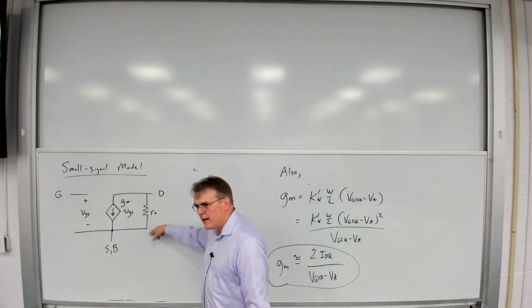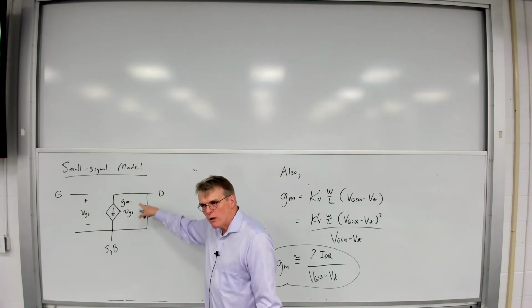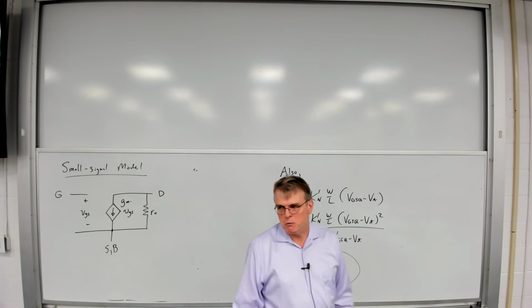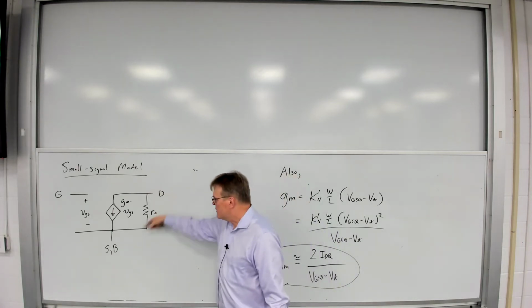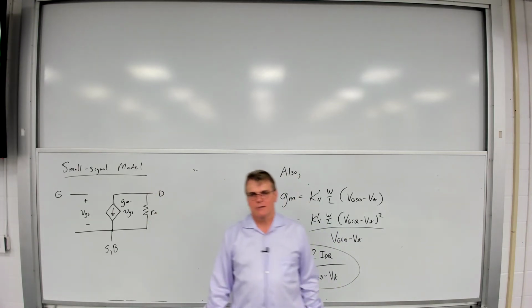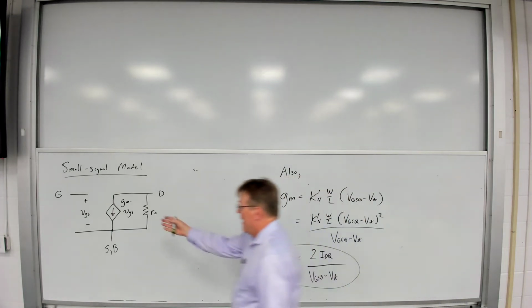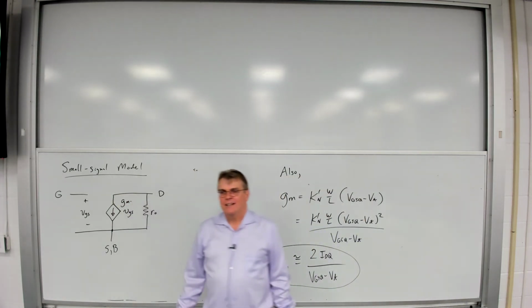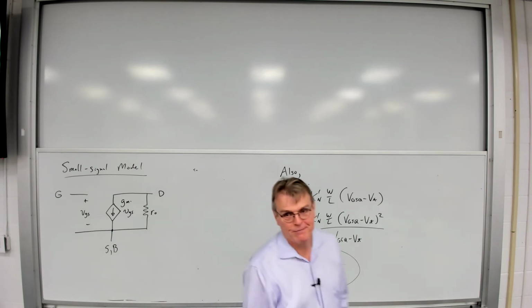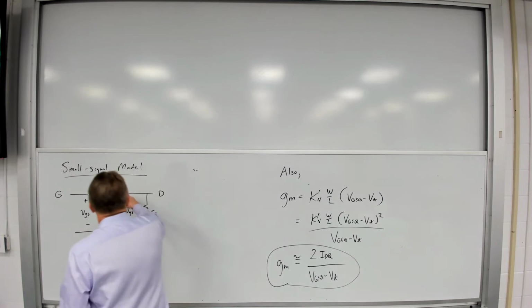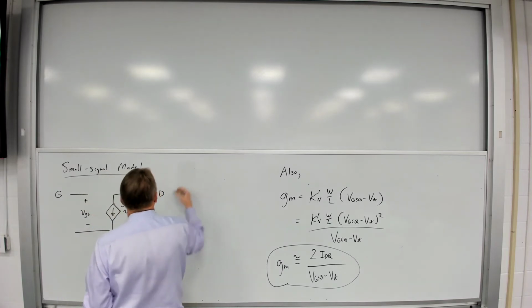And then that non-ideal behavior, we have the extra current between the drain and the source, that resistor models that. So as we make VDS larger, additional current flows through that resistor. And that gives us that non-ideal slope. In its simplest form, that's it, guys. That's the small signal model, two elements. All right? Now, this, of course, was for the NFET.